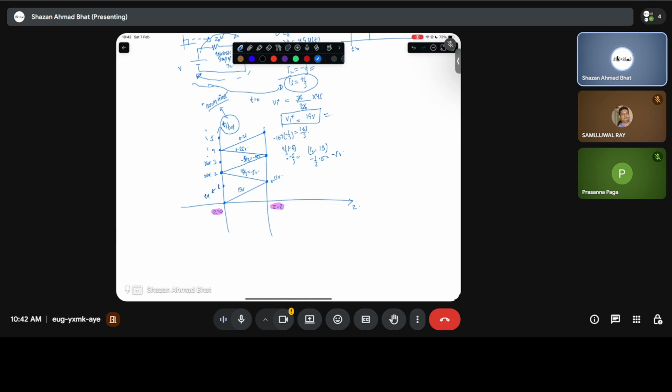So it'll again stay positive because it will be 0.55 times this thing, which is 1 by 3. So it'll be around 0.21. And then it'll again get reflected. But approximately after 5 TD, we assume that it reaches the steady state value. So this is basically 5 TD.